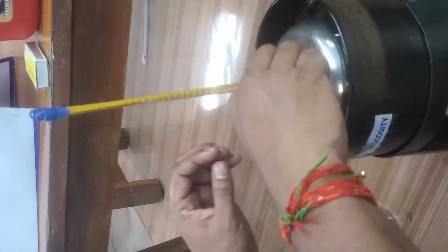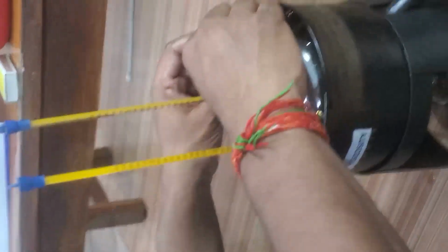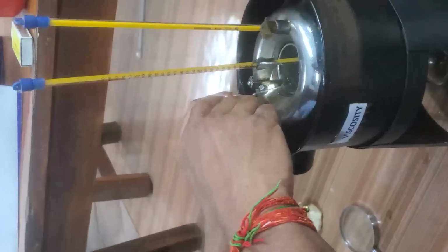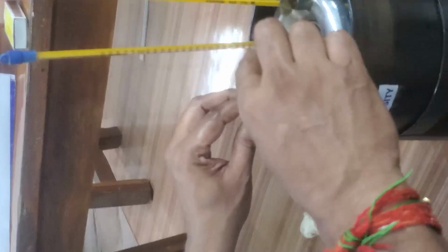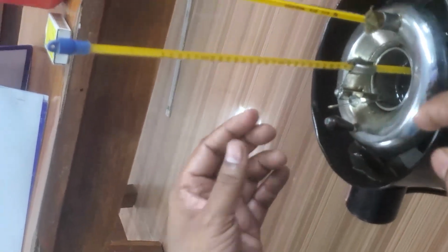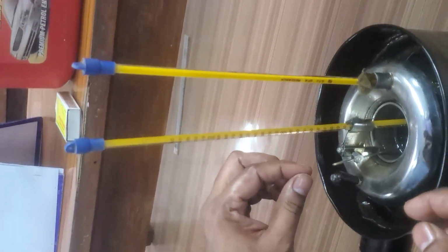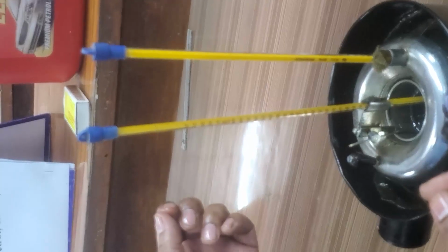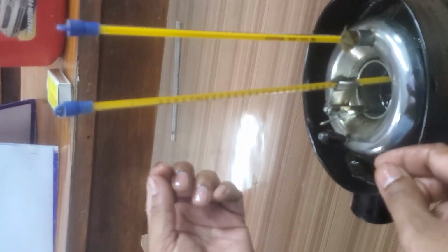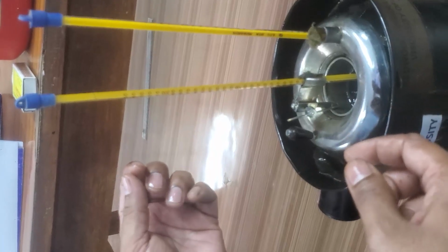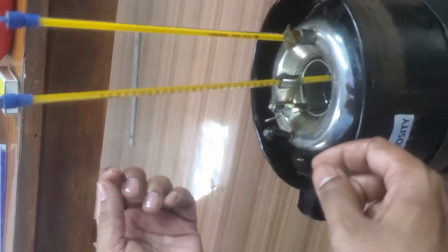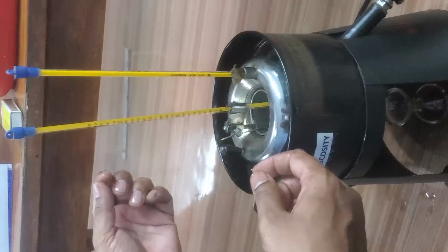This is the precaution we have to take while stirring. Simply we have to do this. Like this, after stirring, once we get the required temperature, with the same procedure we lift this ball and collect that 50 cc of oil in the same specific gravity bottle. We note down how much time is taken to fill that 50 cc bottle. From that we can determine the viscosity of the oil.